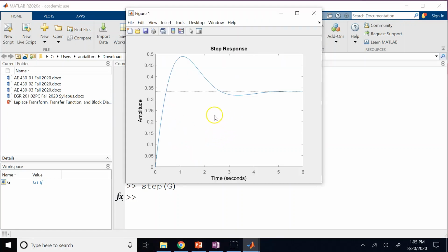And you'll see stability, right? So look here. What do you see? I provided an input of 1 unit, and as you see, my output starting from 0 grows to some number, then goes back and ultimately settles at this constant number here, which is about 1/3, or exactly 1/3.